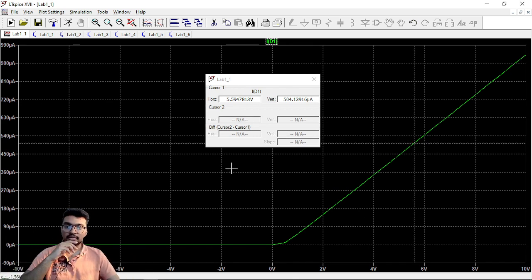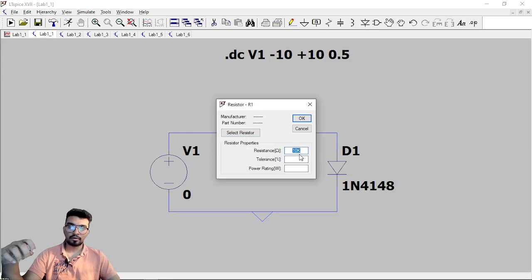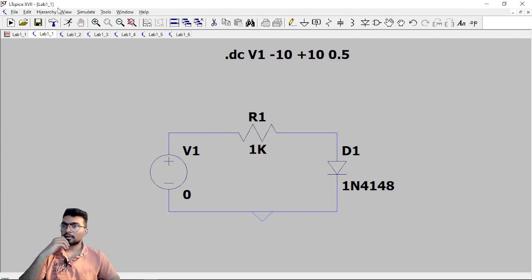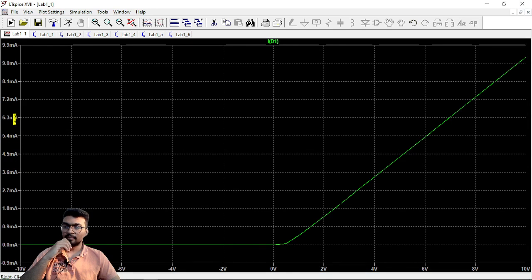Okay, so this is the first question. You can also change the resistance value to lesser values, as mentioned in the question. So you can just go here and change this value. Basically I have put it as 10k, but in the question it was mentioned to be 1 mega ohm, right? So you can just click like this, or you can just make it 1k, small values. Okay, so this is the other thing. You can just click here and the current will be changed by the magnitude of milli, right? So micro to milli it is changed.